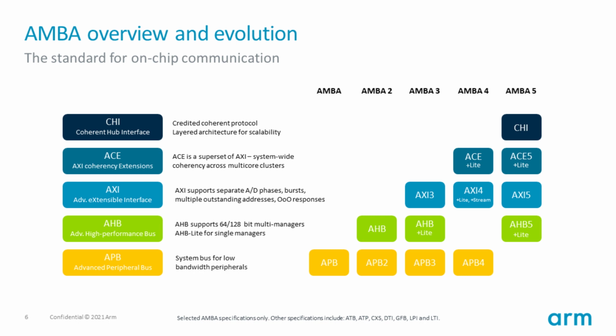Here's a very brief overview of AMBA. AMBA is the standard for on-chip communications. It's an open standard, meaning it's developed collaboratively and it's freely available where anyone can use it. AMBA defines the protocols and interfaces between different components in an SoC, but not the interconnect implementations themselves.